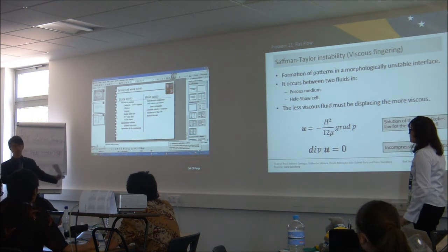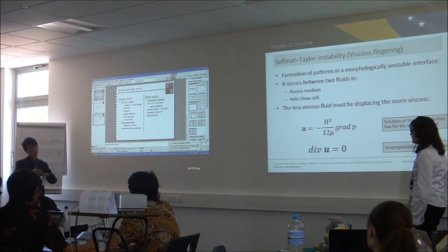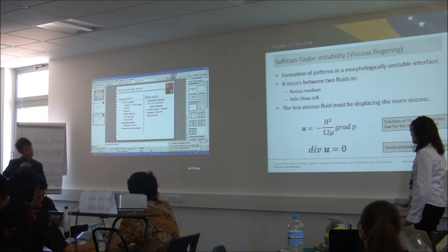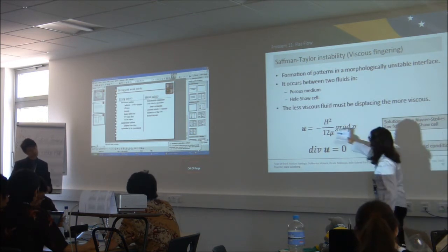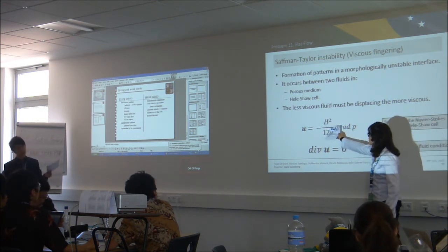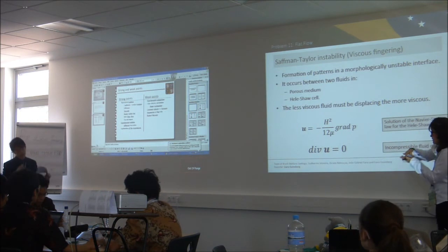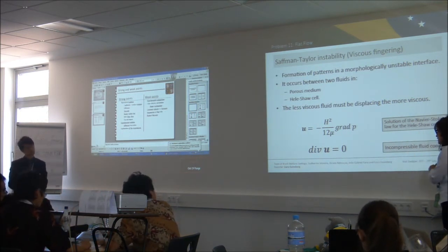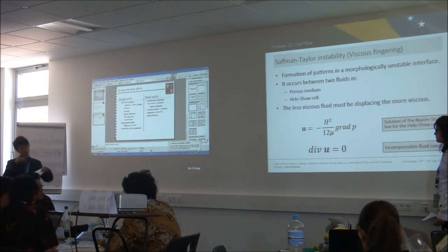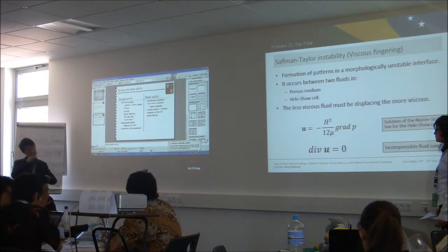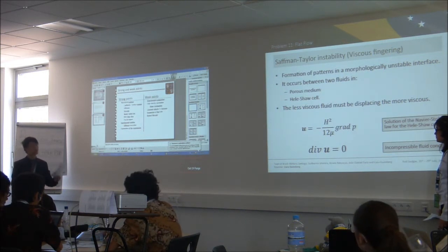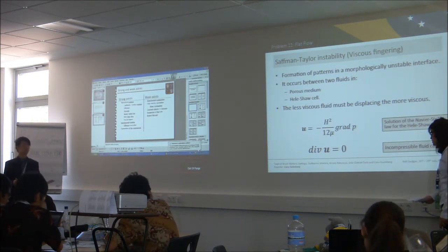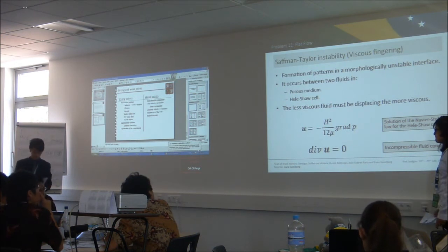I didn't quite understand. So now you say that the flow depends on the gap between the plates? Yes, it depends directly on the gap. If you have a smaller gap, it will be more like a laminar flow, and the approximation will be better. Okay, so when the gap between the two plates is low, then there is a laminar flow. Yes, it can be approximated to a laminar flow. Okay.